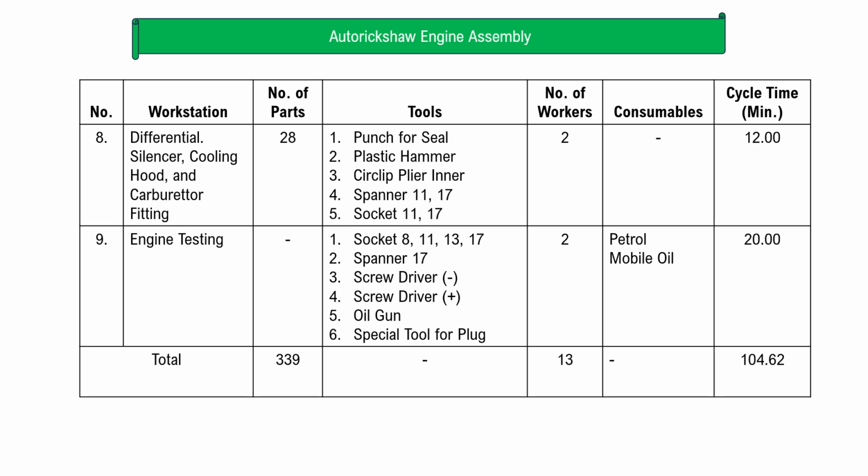And the last workstation, number 9, is engine testing. Over here, we need socket, spanner, screwdriver, minus and plus, oil gun, and special tool for plug. 2 workers are employed, and the consumables required are petrol and mobile oil, and the cycle time is 20 minutes.